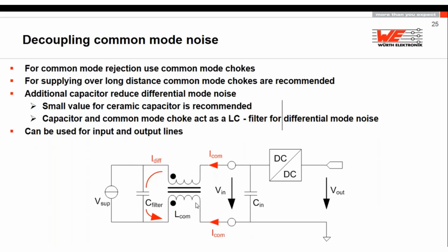And beginning from this point, the common mode choke is just a heavy component on your PCB. It's good for the kilo, but it's not good for the EMI. You go inside of the PCB with the common mode choke, and after the common mode choke, you declare this is your own clean ground. It has a galvanic connection to the output, but only through the coil. Everybody in your device must talk to this leg of the common mode choke. It means to its pin. It means the same ground point.